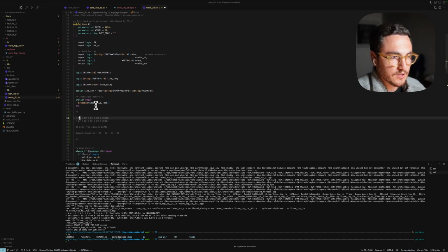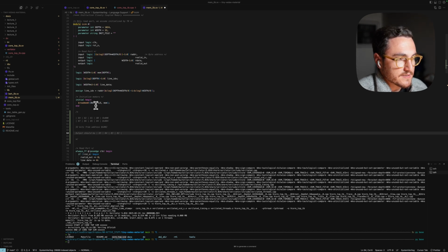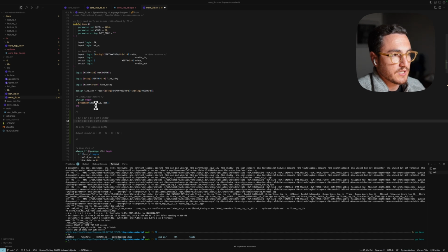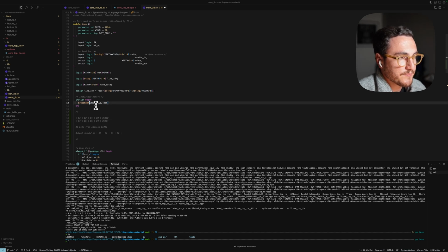If you have a word aligned memory, but you are able to address the bytes, you will always face this issue, both in reading and in writing. This is going to be the ultimate reason why we're going to need a queue inside the load and store unit of our processor when dealing with the DCCM, the data memory. So how do we fix this? Instead of fetching 1 line at a time, we fetch 2 of them and we concatenate them.